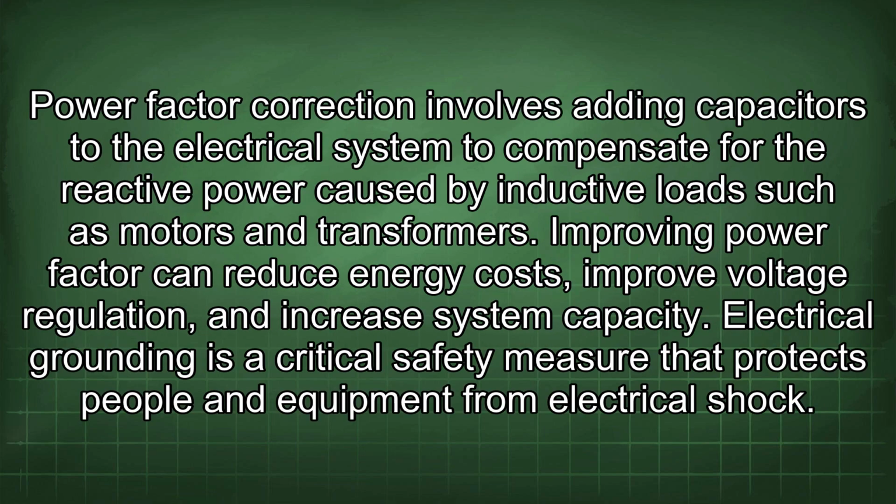Power factor correction involves adding capacitors to the electrical system to compensate for the reactive power caused by inductive loads such as motors and transformers. Improving power factor can reduce energy costs, improve voltage regulation, and increase system capacity.